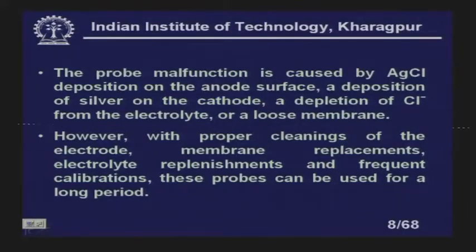We have seen the polarizations, all those things are there. So, it needs repeated cleaning, then replacement of the electrolytes, or it is supplied from a permanent reservoir. That type of thing and frequent calibrations will make the sensors usable for a longer period of time.